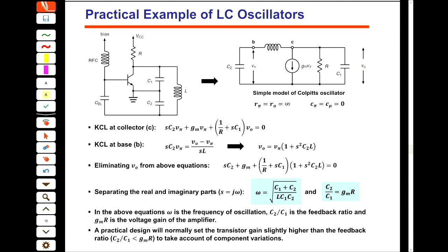So if we look at the small signal model for an oscillator, is this a Colpitts or Hartley? Is this oscillator Colpitts or Hartley, or none of them? Hartley? Why? Yeah, it's Colpitts because it has two capacitors and one inductor. So this is Colpitts.